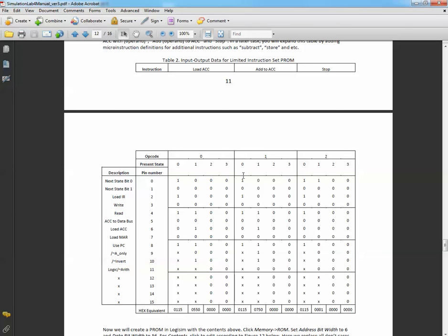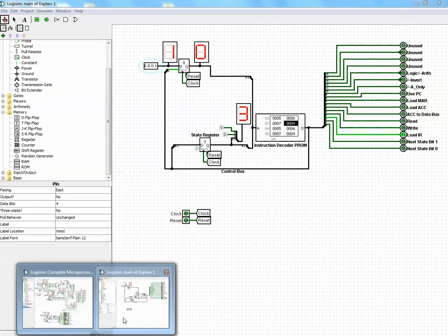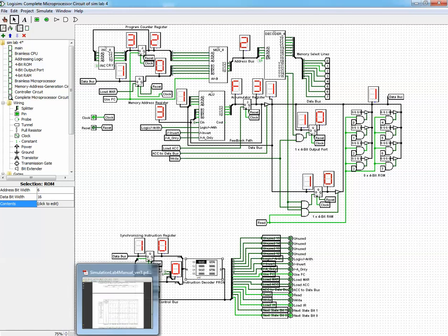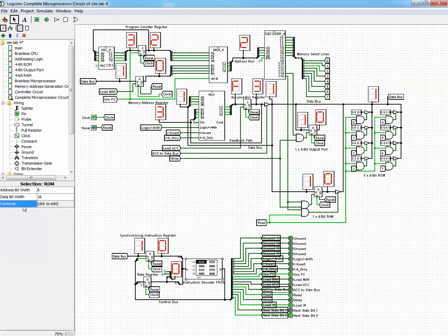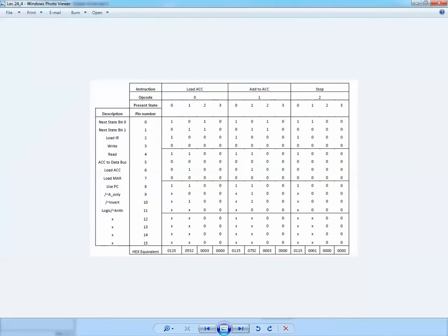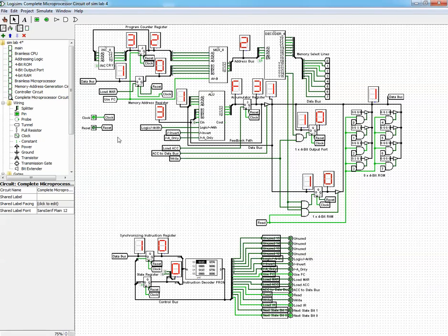Again, here we want to load IR, the instruction register, by 1. What is the instruction register? The instruction register is this register. We want to load it so that it controls exactly which command you want to execute. Do you want to execute this command or this command or this command, and so on and so forth. Once you do that, you take the clock again.